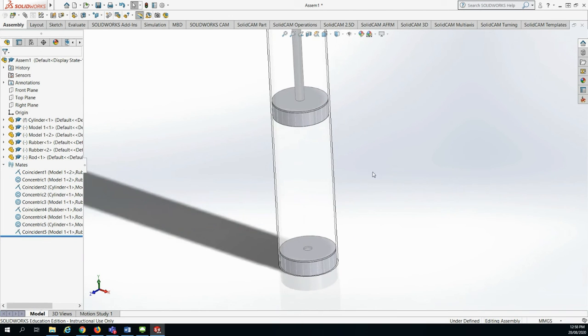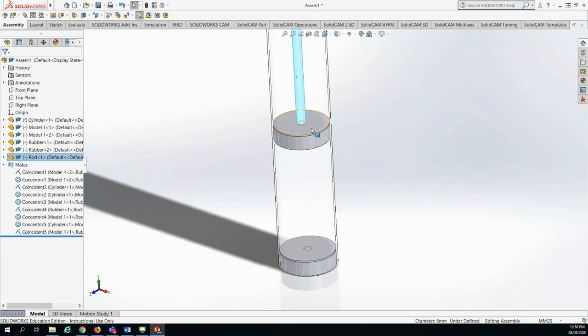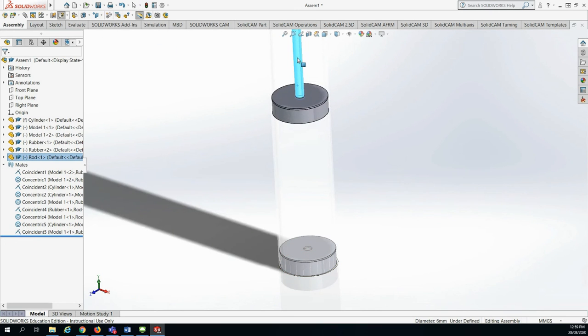Okay, now what happens is that if I pull the rod up, this will be held because we have some water above here, so this will close it down, and this will be open because we are going to have negative pressure in this area. Negative pressure will open this rubber, take it up, so the water will come from the source, fill this chamber. This one is closed.